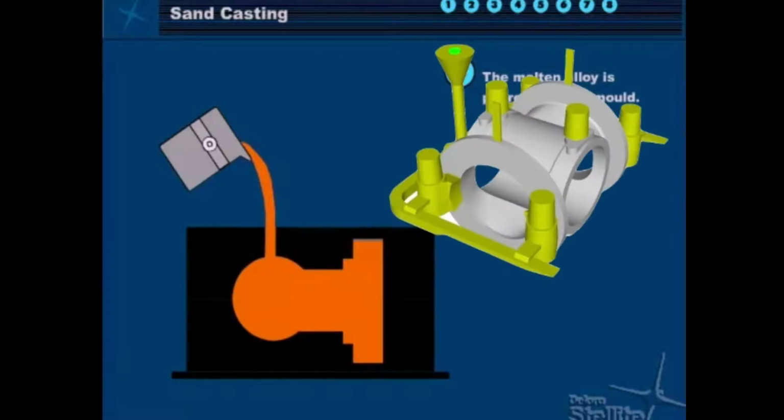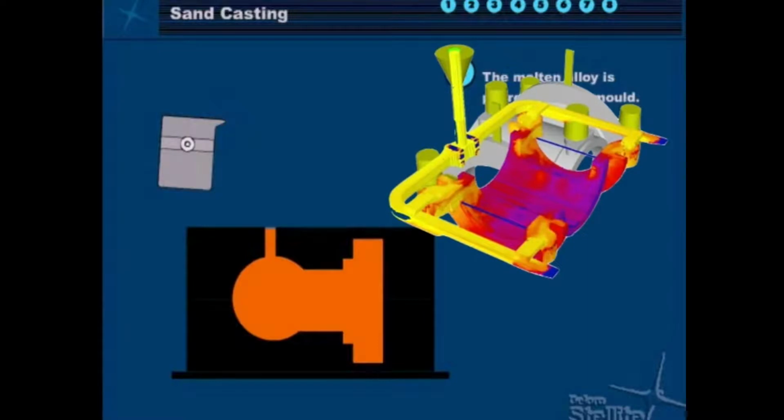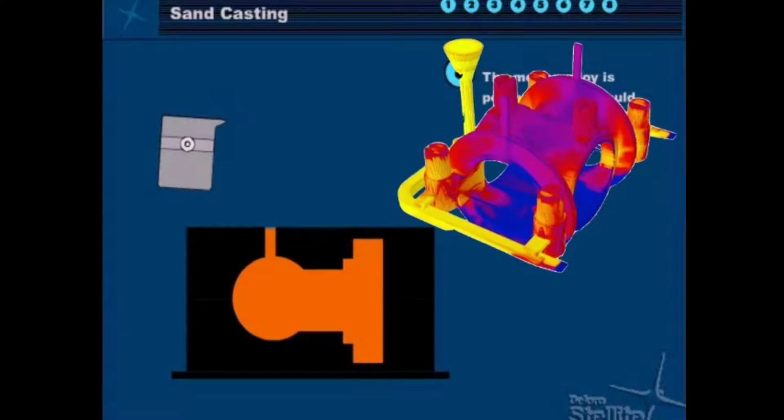The inset shows a stainless steel valve made in sand, as it really would be, with the cored hole, and the mold filling sequence shows how the engineering of the liquid metal delivery is part of the way the solidification for integrity of the valve is established. So this representation of a horizontal sand mold is what it would really look like.